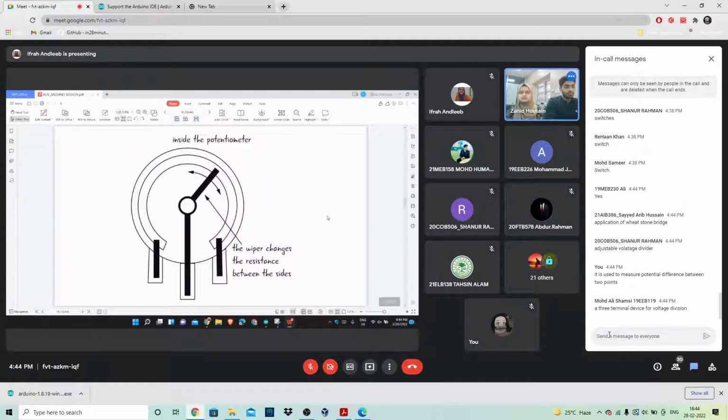So this is the potential resistance strip. ये carbon की strip होती है, where there are 3 terminals in this. So ये जो wiper है, जो आप देख सकते हैं, इसे आप जिस भी टर्मिनल के अंदर रखेंगे, वो उतने पार्ट का रेजिस्टेंस आपको अवेलेबल हो जाएगा. So these two extreme terminals are for ground and plus 5 volt, and this middle terminal is for analog input, analog reading actually.